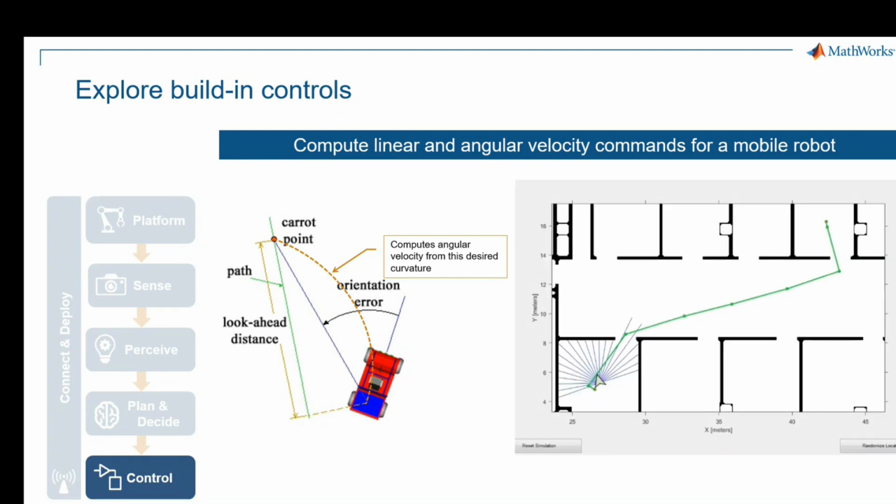However, if you put, for example, an obstacle in front of this controller, of course, it doesn't take it into consideration. It's just trying to follow the path from the planner using the controller as it was defined. One way to actually add some logic, let's say there is an obstacle in this path and we want to stop because of this obstacle or change the trajectory, is to add what we call a supervisory control.